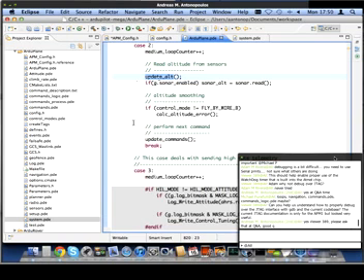And you see that update out function, which you can see is called at 10 hertz. So you might think that means we're reading the barometer at 10 hertz. Now on the APM1, that is actually true. We are reading the barometer at 10 hertz. And the reason for that is we don't currently have an interrupt-driven I2C library, which means we have to poll I2C devices, and the APM1 barometer is an I2C device, which means we have to call from the main loop when we want to read the barometer.